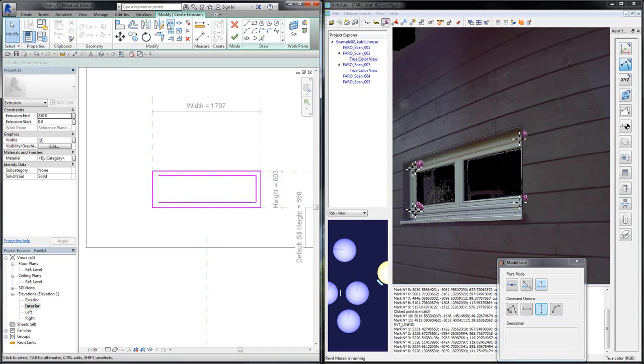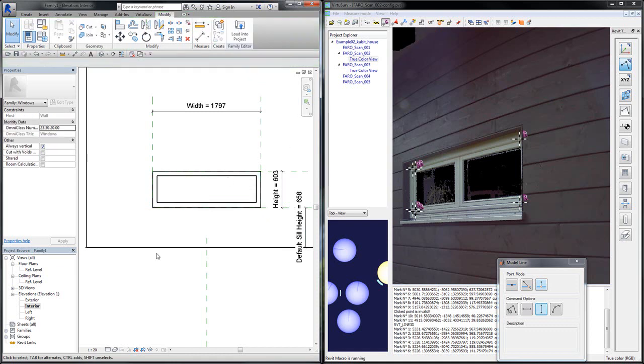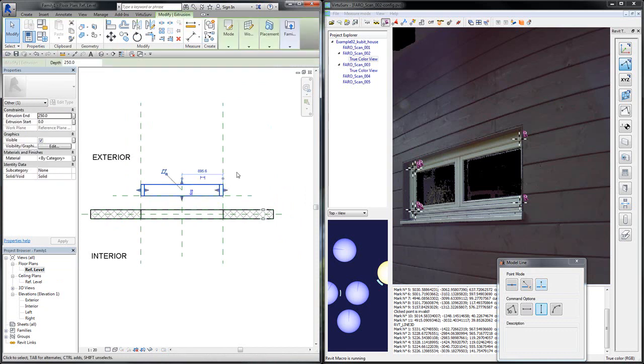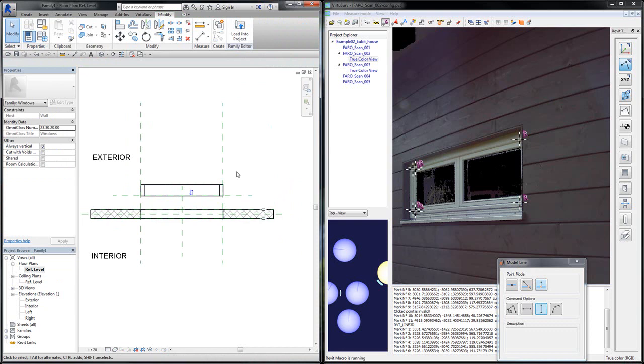Okay, and again with the pick line tool I will pick the other 3 lines, trim the corner, okay, and I choose the mirror tool, select the edge and draw an axis at the middle of the opening rectangle. Okay, and last I will trim this again. Okay, now the sketch for my window frame is ready, and I can finish this editing mode with a green check mark. And let's have a look to the reference level, and you can see here this is our extrusion object.